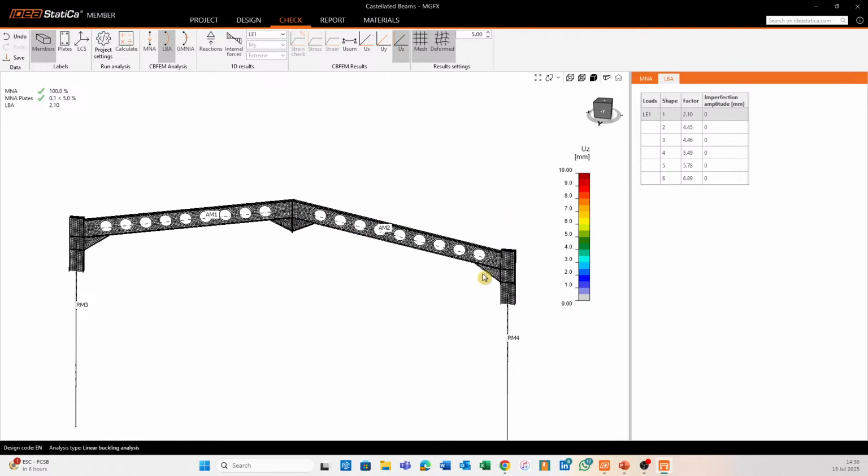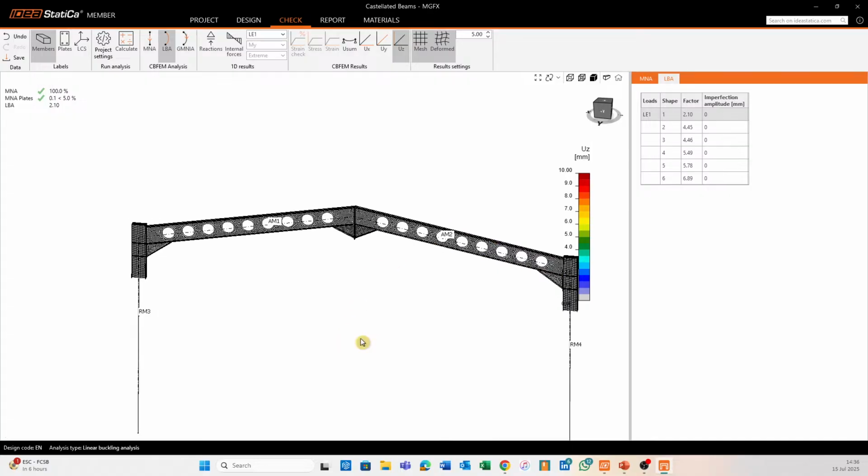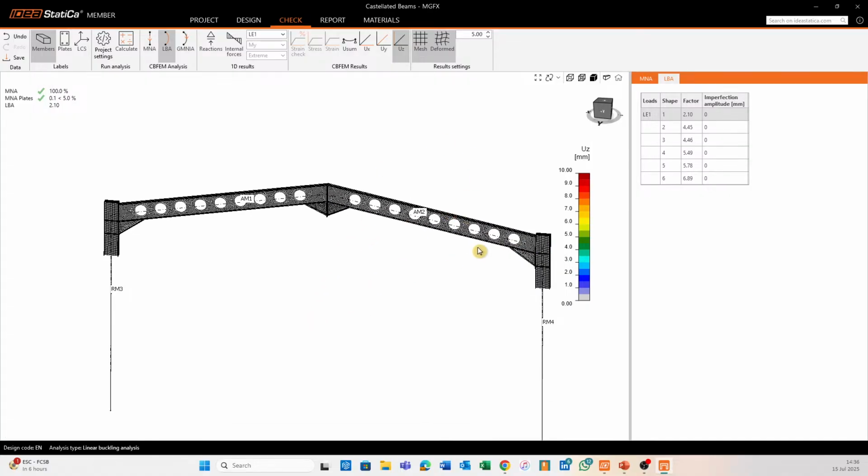Okay, so this is all stuff that is recorded within the Eurocodes. And if we have time, I might even go there and show you where those are. Okay, so I'm going to calculate these. Again, this is more of a complex topic, and it would deserve a webinar on its own, but it's highly theoretical. So if you want more information on this, you're more than welcome to write me an email. Based on what I could see and what I could calculate, the imperfection amplitude is 41 millimeters.